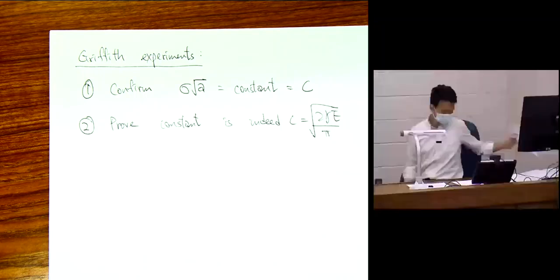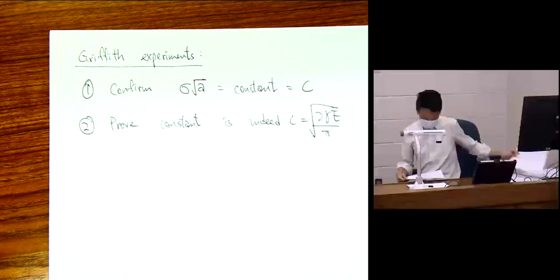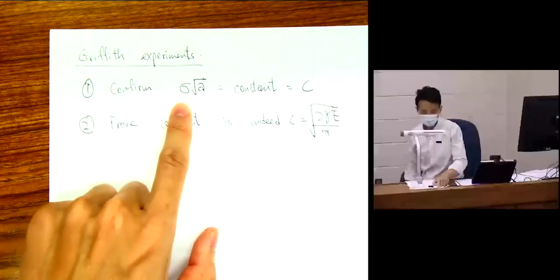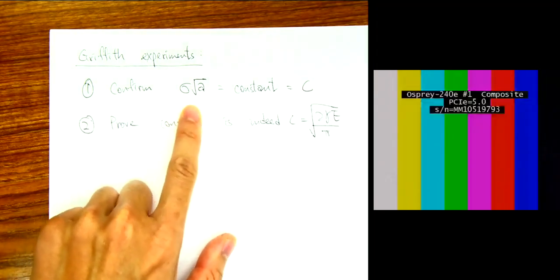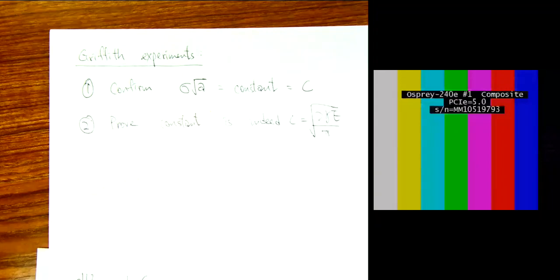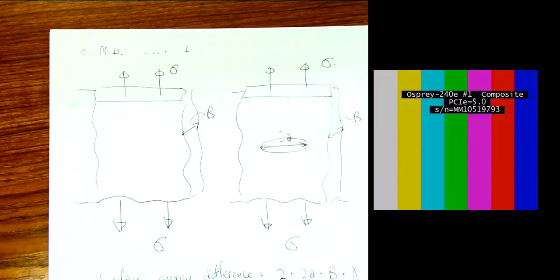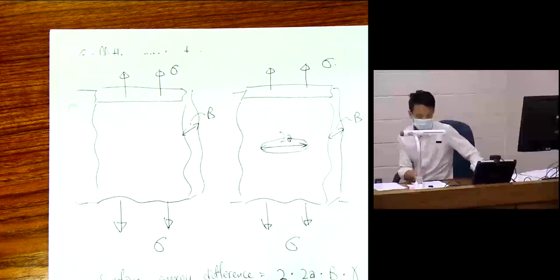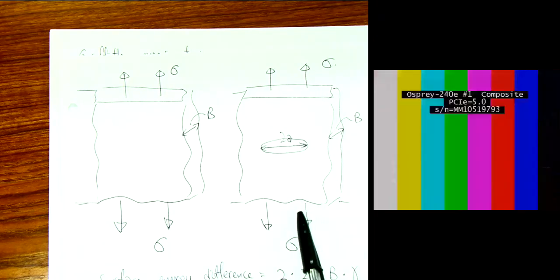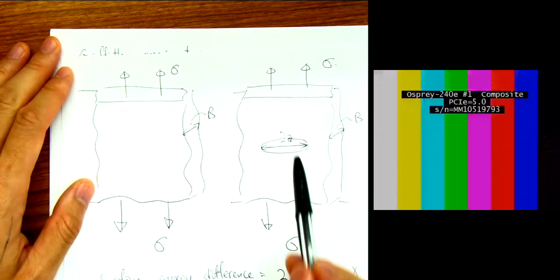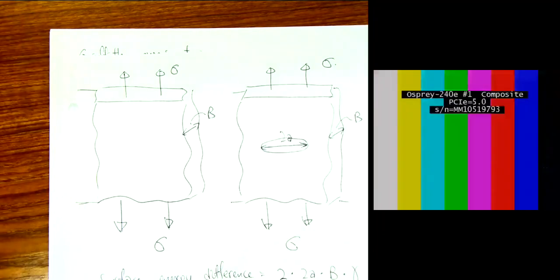Okay, this picture here. So remember what sigma is. Sigma is the fracture strength, right? And A is the crack length, right? So again, let me remind you, this is the picture we're looking at. What I need to do is create several pieces of a glass plate. He used glass because it's linear elastic, very brittle. And he made cracks intentionally on each of these plates, right?